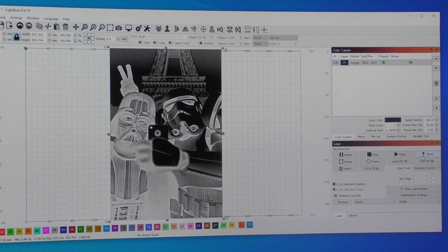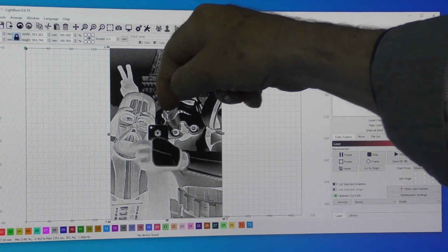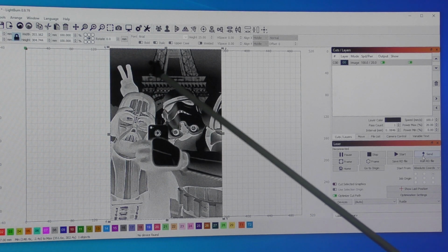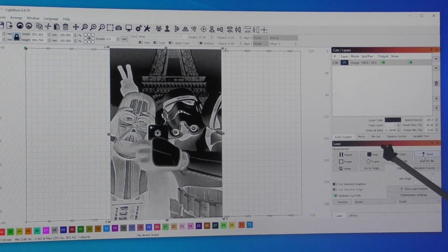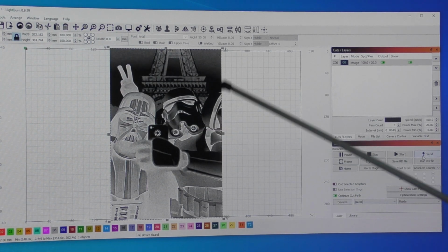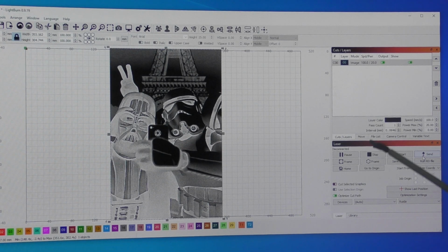What I'm really now doing is creating an aliasing pattern. LightBurn is going to turn the tube on and off for every single pixel that it sees. So there's going to be no problem in the x-axis, but the problem is going to be in the y-axis because he's stepping at a rate which doesn't match the pixel size. So you're naturally going to generate bands in the y-axis because of this difference in the pixel size and the y-axis step. Haha! So that's the reason why Matthew is getting banding. No, it isn't.